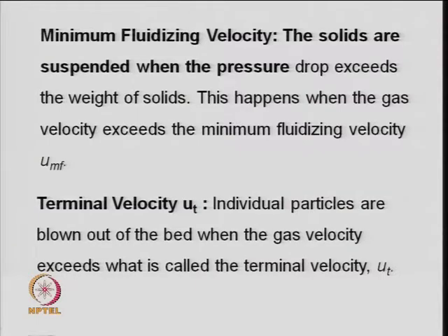So, this is based on what the pressure drop in the bed will be at those conditions, right. So, fixed bed, then fluidizing, and what conditions are required to make the bed fluidize continuously, what is the elutriation or loss of particles, what is the residence time, or what hydrodynamic study needs to be done, because when you have a mixture of particles, different size particles will have different degrees of fluidization, right.